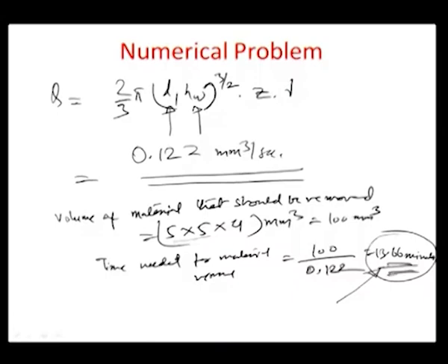We should keep in mind that this is a theoretically predicted time, but if you look at the actual time of the process, the actual time is much more than the theoretical time, because we are assuming that this process is 100% efficient. That means one impact is producing one flow, but that may not be the case. If there are a lot of abrasive particles packed in the slurry, there is a possibility of intergrain collisions, and collisions with the debris which gets generated, and there is a huge amount of chaos or randomness in the system of the particles and debris floating around in the slurry material, and therefore,